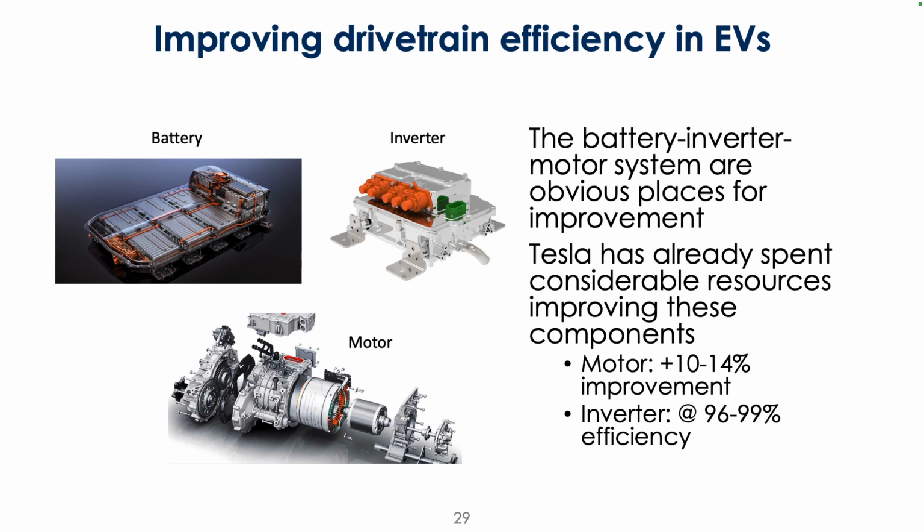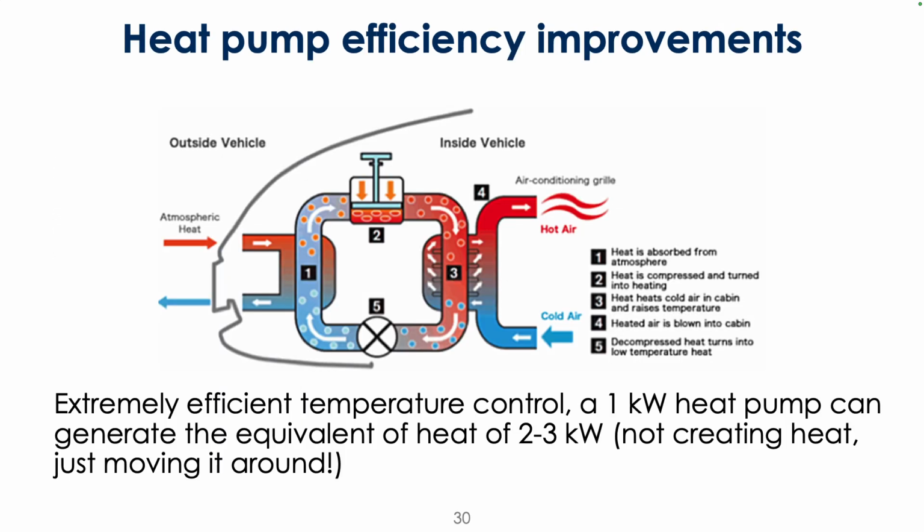The other big one: you may have heard of electric vehicles losing a lot of range and efficiency when they operate in cold environments. That's one of the common drawbacks that you hear in media. If I live in New England in the winter, I might lose 30 to 40% of my range. A lot of that has to do with the inefficiencies of electric heat, which is the primary way that you have thermal management of the battery.